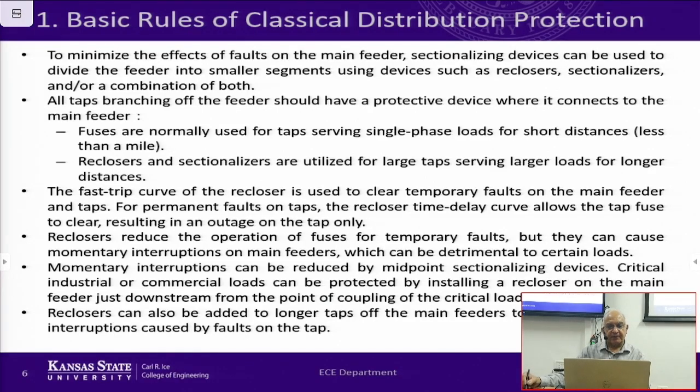I think these are some approaches to placing reclosers. We talked about how fuses are normally used for taps serving single phase loads for short distances. Reclosers and sectionalizers are utilized for large taps serving large loads for long distances. And again, this is the same idea that we talked about: for momentary interruptions, the recloser operates first and then lets the fuse operate later on.